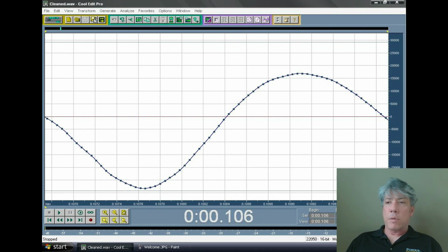If you have a process where you've got some heating process and you're measuring temperature, the temperature range is going to be set that maybe you need a 1,000-degree range. Well, a 1,000-degree range, if you have an amplitude resolution of 65536 or 16-bit, all you have to do is take the 1,000 degrees and divide it by 65536, and that's how much the temperature would have to change before you'd recognize that the temperature had changed at all, because it's been discretized in amplitude. You should grab your calculator and run through that just for fun. 1,000 divided by 65535 or 65536, it doesn't really matter, take your pick.